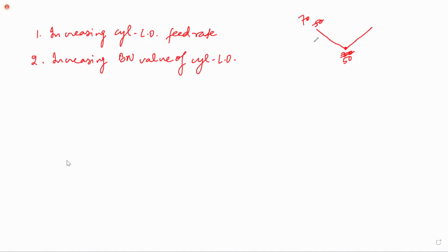Then one more thing which you need to see is the wave cut pattern in the cylinder liner. Two more things you need to see actually. Is the lube oil flowing out from the lube oil quill without obstruction? What happens sometimes, the cylinder liner gets worn out and this quill, the hole through which the oil drains out, gets partially covered. Also the wave cut groove gets partially filled up because of the wear taking place, and this groove does not remain of sufficient depth. The depth of the groove is lost, so it is not able to retain sufficient quantity of oil.